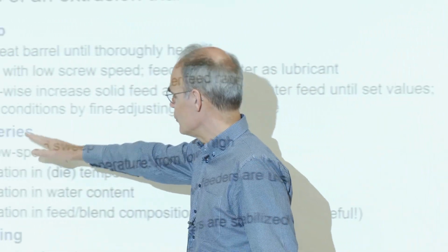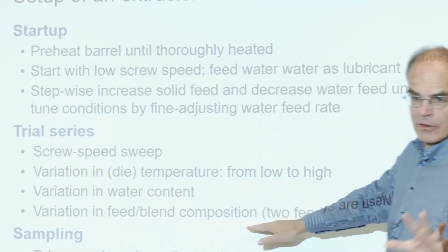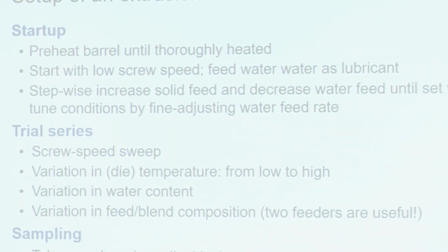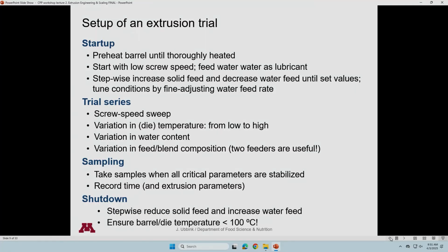And then, of course, if you do a trial series, especially in research and R&D, you very often want to run multiple blends and blend compositions. That's typically something you have to plan very diligently, especially if you have one feeder.